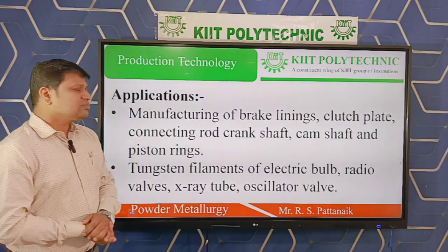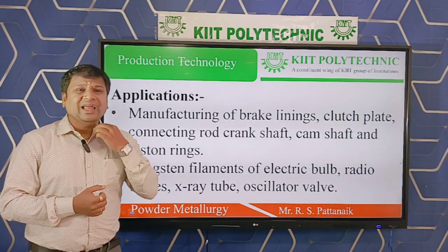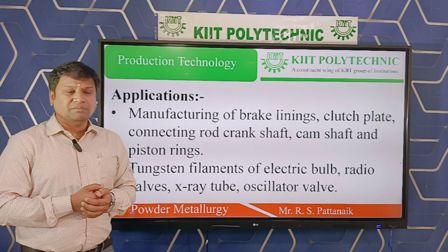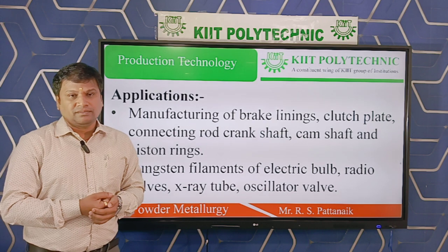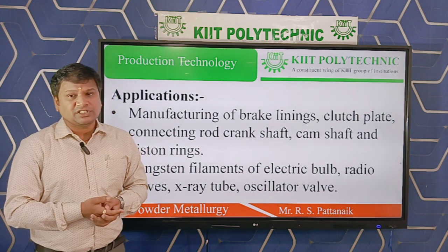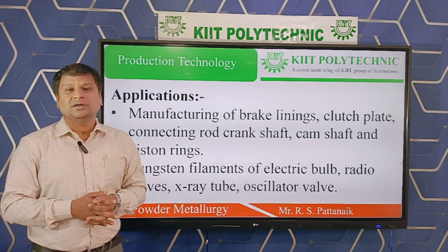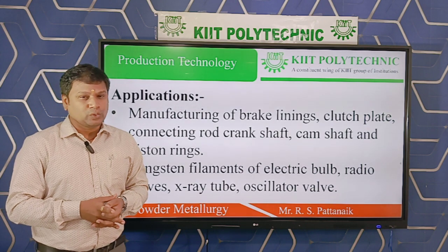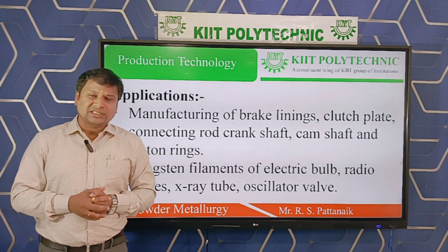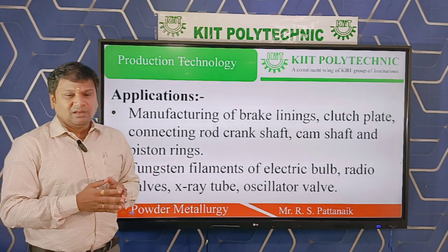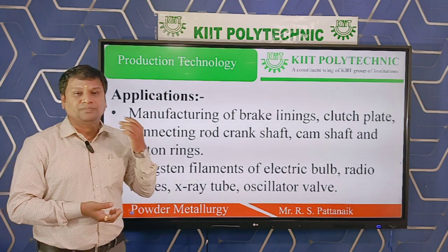Okay, now there are also some disadvantages. In the powder metallurgy technique, metal powders are very expensive. In some cases the mechanical properties as well as physical properties are not as good as, for example, casting. The powder metallurgy technique is basically limited to small sized parts. So these are the disadvantages of the powder metallurgy technique.